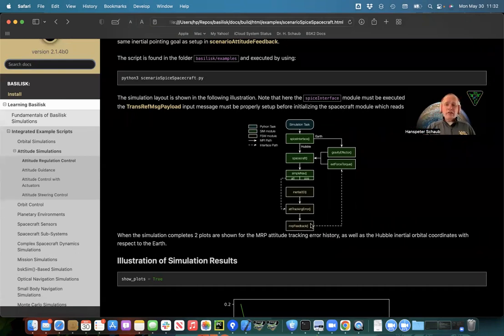If you didn't care about transients and you just want to go, you know what, if I'm simulating the feedback control, I can only simulate with a small enough time step so I don't have digital instabilities occur. What if you wanted to take 1 minute time steps? Then this control wouldn't work because that's way too big a time step for these gains to work out. You could just take inertial 3D, take its reference and actually connect it directly into the spacecraft.